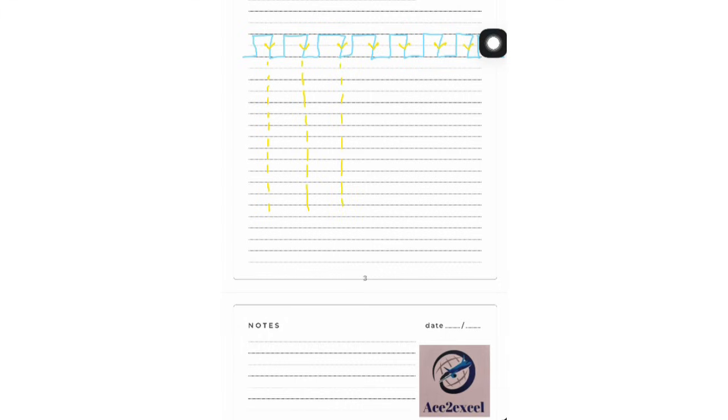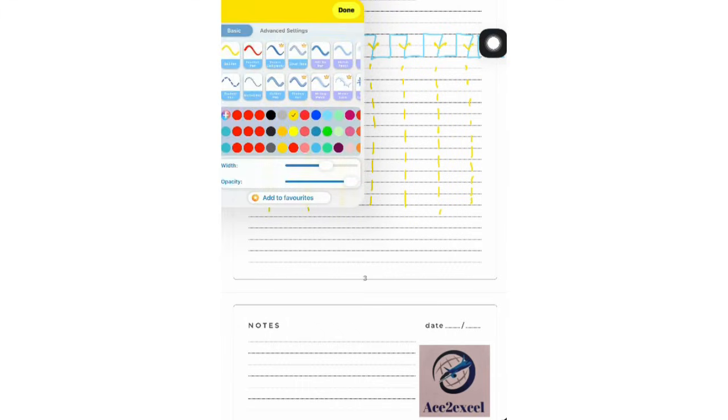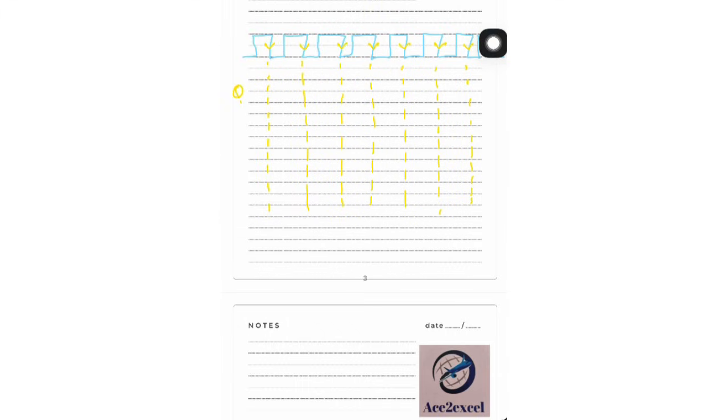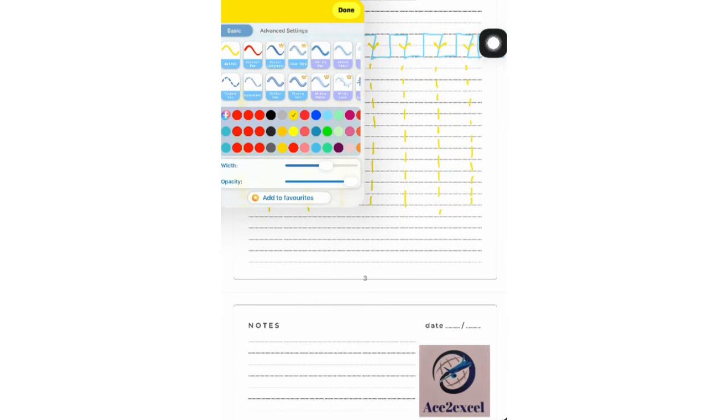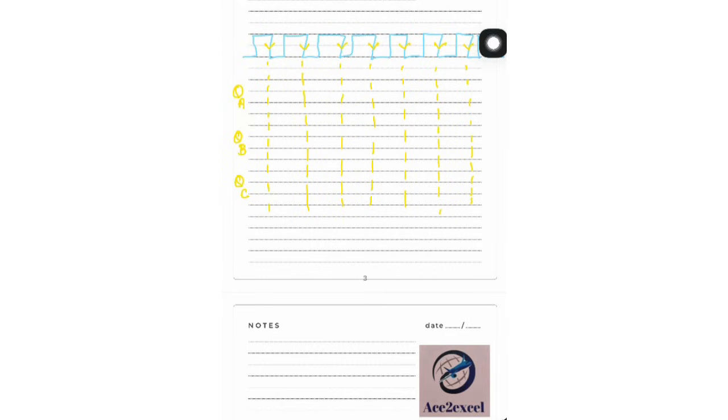In our circuit, we have 3 flip-flops. QA will change its state depending upon the external clock pulse. QB will change state depending upon the negative edge of QA. QC will change its state on the negative edge of QB. Now, first we'll make the first output, that is QA. QA changes its state at the negative edge. At every negative edge, it will change its state from 1 to 0 and from 0 to 1. That is, the output toggles.